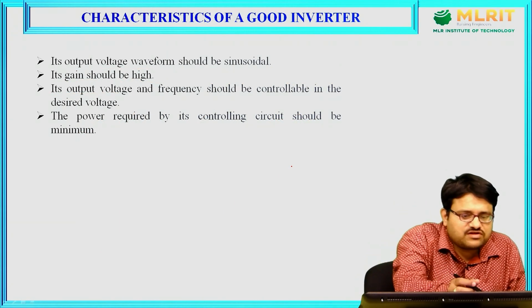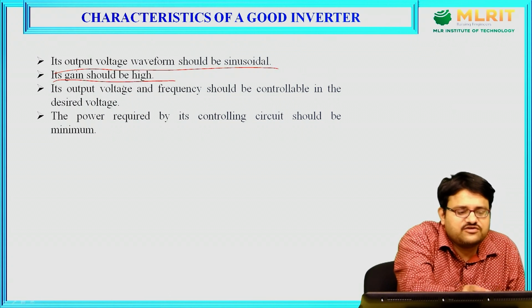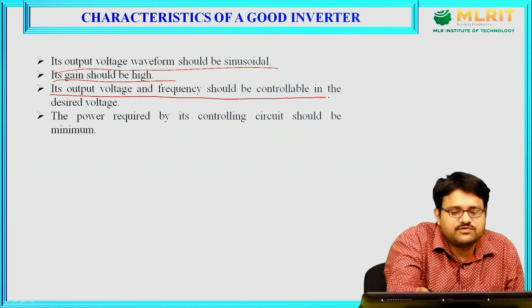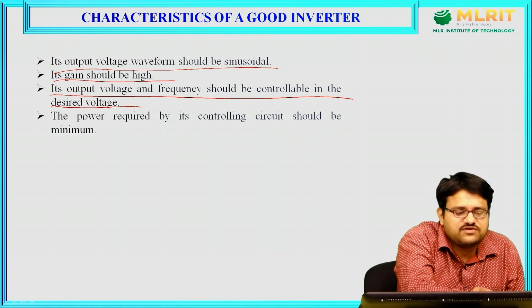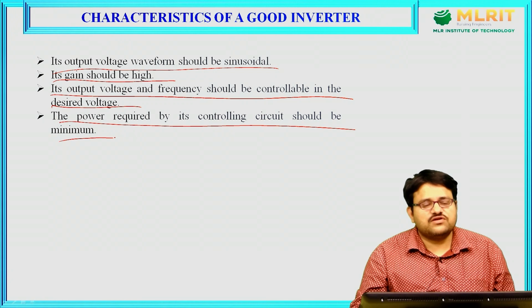Characteristics of a good inverter. Its output voltage waveform should be sinusoidal. Its gain should be high. Its output voltage and frequency should be controllable in a desired range. The power required by its controlling circuit should be minimum.